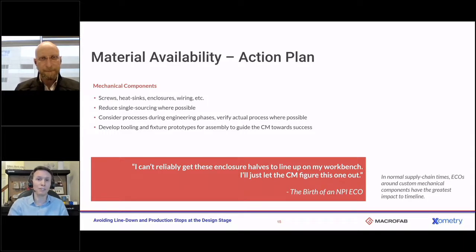Right. If you have the opportunity to do that, especially when you're working through work instructions where you're just thinking, hey, this should slide into this, CNC turn shaft here, and you can actually try it. Or if you're buying off-the-shelf extrusion and post machining that for your housing, it could give you a lot of information very, very quickly and relatively affordably. It's like an insurance policy there.